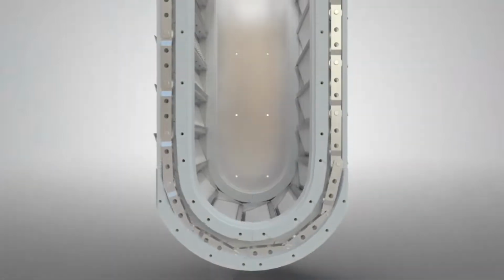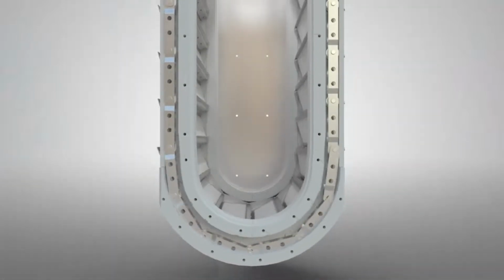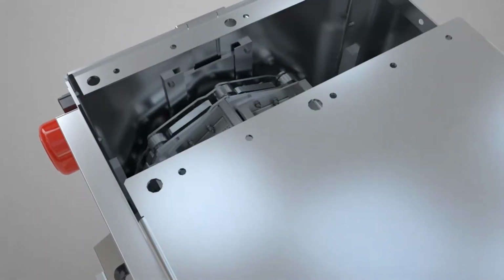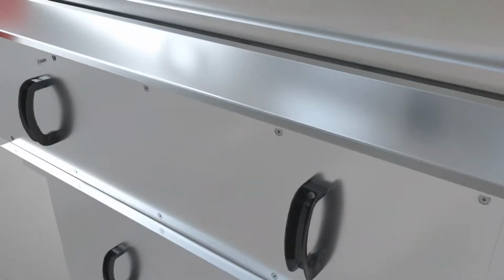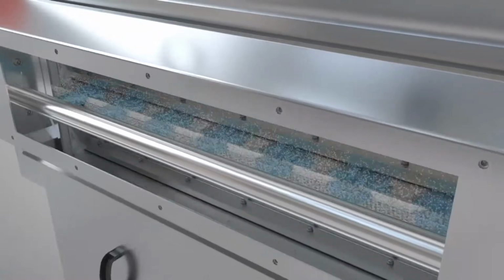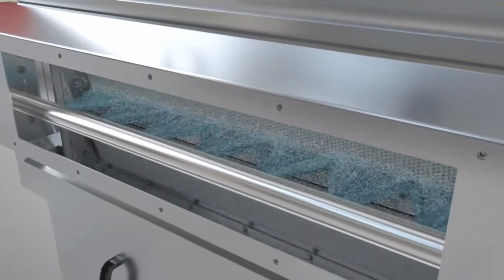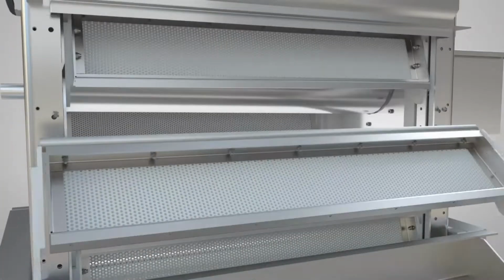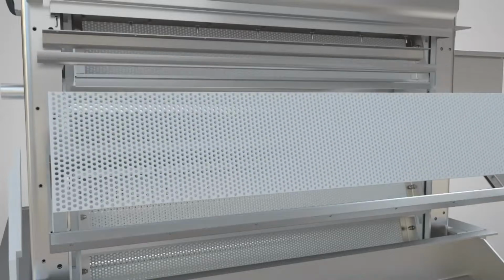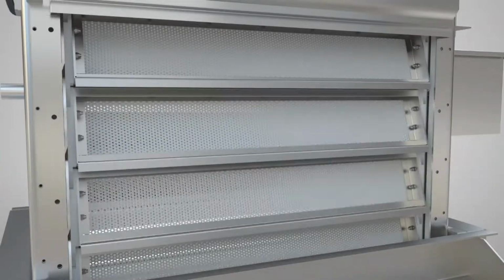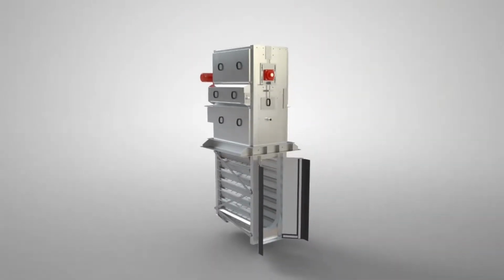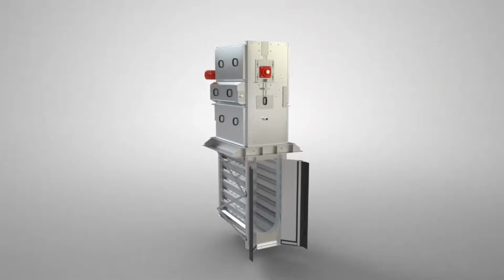If you wish, you can also put the invert of the channel coincident with the bottom of the inverter here, so that you get flow directly into the screen itself rather than through a step. This shows just the simple sprocket at the top driving the screen chain, and the wash water washing the debris from the outside to the inside this time into a launder in between. Again, panels can be easily replaced. These are ultra high molecular polyethylene, so if they do get damaged, they can be readily removed. Okay.